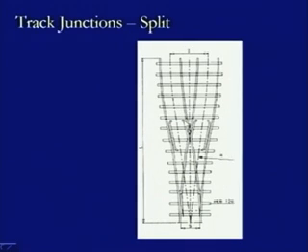There is an acute angle crossing, and at this acute angle crossing we have these as wing rails. We can see these wing rails and a pair of jack rails being provided, one on this side and one on this side. So, that is a pair of jack rails, and we have the points, that is we have the tongue rail being shown here like this, and this is being shown here like this with the ending as a black one and connected by a dotted line, that is a stretcher bar. So, at this point when it is being shifted with the throw off switch provided on this side, it means it is providing the movement on this track. But if the throw off switch is on this side, that is towards the right hand side, then it will be providing the movement on this track.